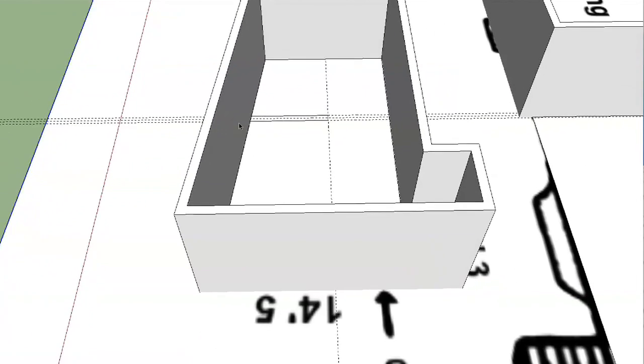So I'll go ahead and switch to the line tool, and I'll draw that. I'll draw a line across here to mark where I want the edge of my wall to be. And then I'll take another line, and I'll just stretch it back. I'll lock it to the green axis, and I'll stretch it back until it hits this wall right here. Good. And then I'll do the same thing over here. These two line segments are going to be different lengths because the wall is at an angle, but you can see once I do that, it fills in the floor.